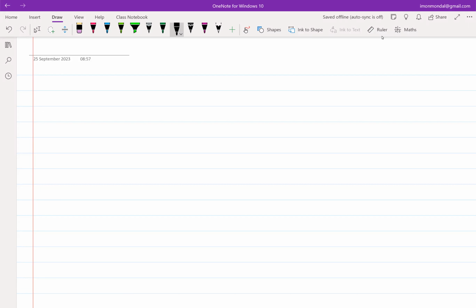Another problem is the gain is gm times RL. gm is a function of threshold voltage and a function of mobility, at least in the simplistic current equation that we have been using till now. Then the subsequent problem is that mobility and threshold voltage are strong functions of temperature, which means that your gain becomes a function of temperature.